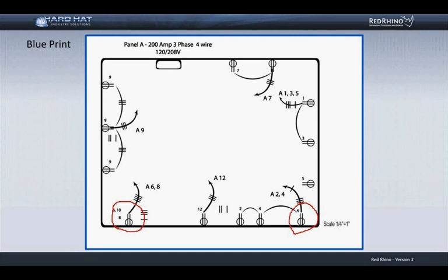You can literally input all the half-inch EMT conduit runs with 3 number 12 wires for the entire job in one single entry into Red Rhino. I know I'm belaboring this point, but if you understand how to take off branch circuit conduit correctly, you'll double your estimating speed when estimating projects.